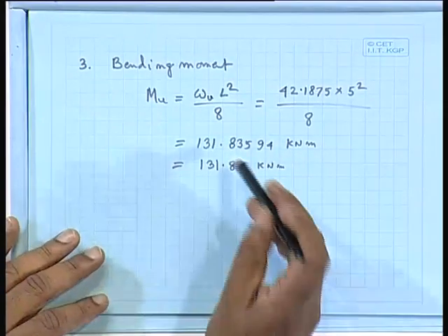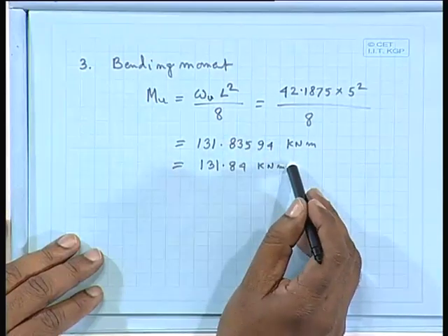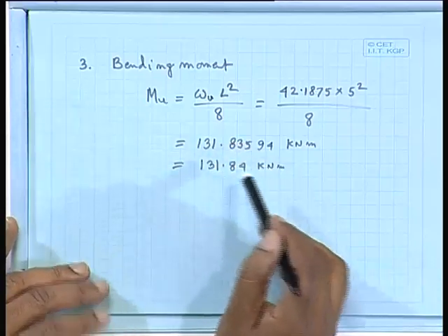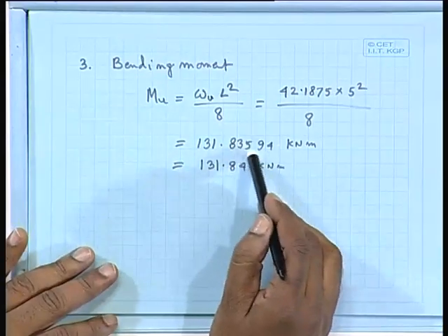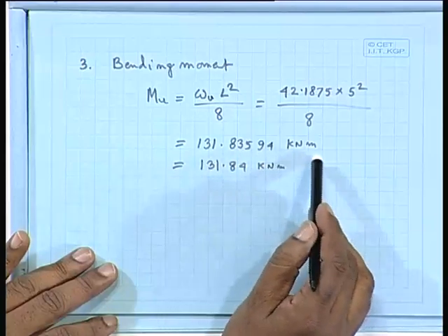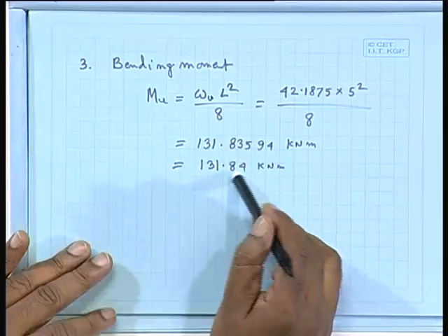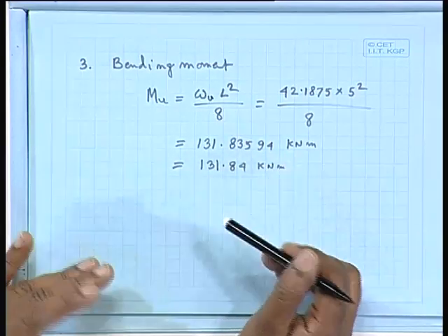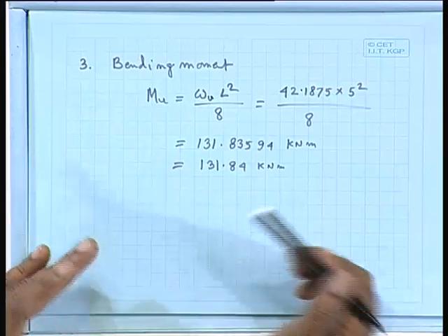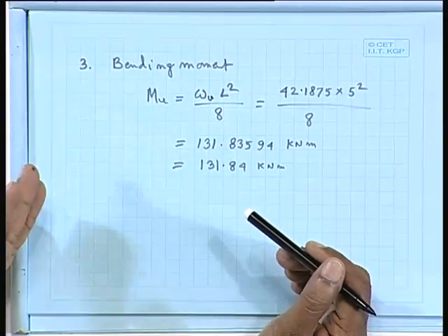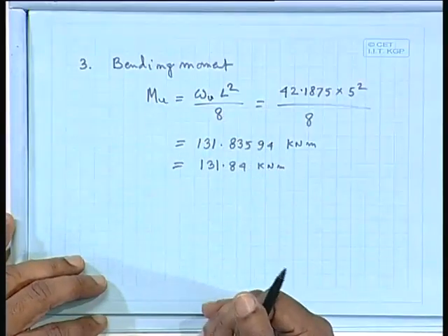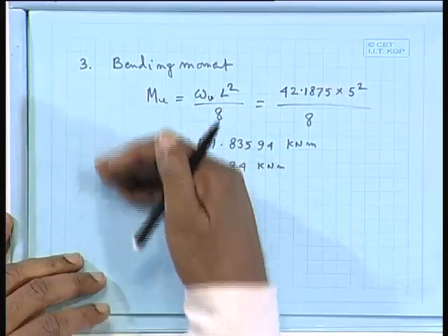Now in that case we can go as far as possible, but in the very beginning we can write whether we have gone up to 2 decimals or 3 decimals, because otherwise it will unnecessarily take time. We can round up to 2 decimals when talking about kilonewton meter. Similarly for meter, we can go up to 2 or 3 decimals, because up to millimeter we can go. If it is millimeter, then we can go only 1 decimal, or keep it in millimeter only. Those things we can write down in the very beginning of the design note, that these are the things you have followed.